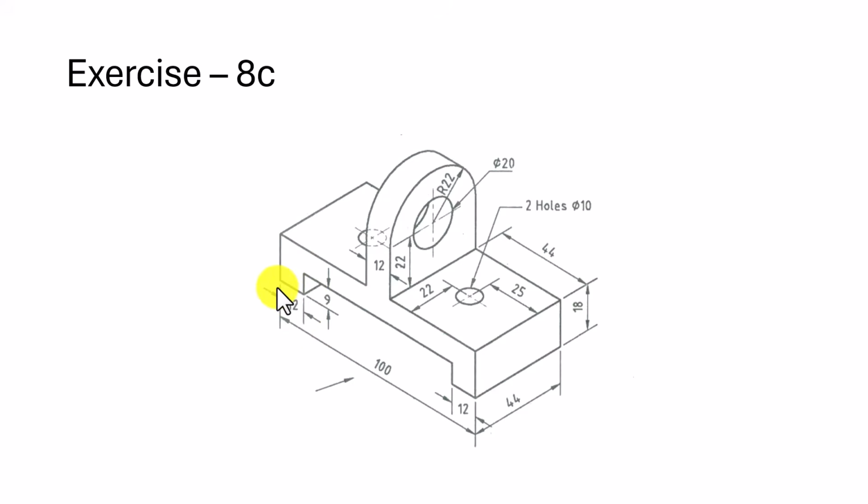So this comprises two different extrusions. One is the basement. This is the profile of the basement, which has to be extruded for a distance of 44 mm. Then another profile is exactly perpendicular to it. We have to make sure that this extrusion is done in a symmetric way so that this can be easily drawn on the center. So let's try to create this solid by using Autodesk Fusion. Let's jump onto Autodesk Fusion.